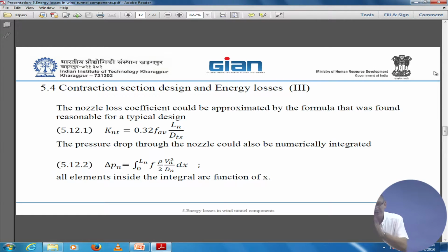Another recommendation coming out of your question is, if you don't know really what your need will be for intensity, keep another drawer empty. Or put as many as you want at the beginning and just take out when you don't need very low turbulence intensity, so as not to lose energy. I think we're a bit innovative in this. I haven't seen too many wind tunnels that have this option to control the number of meshes and screens.